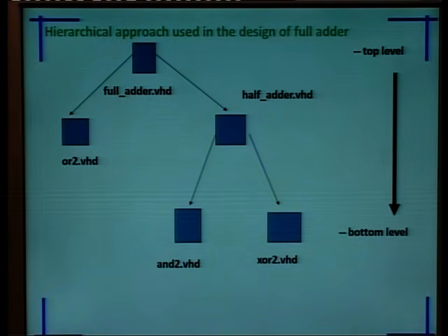In the bottom up approach, we have to start from the device, which may be NPN, MOSFET, PNP type, and from the device we go for the circuit design. From the circuit design we go for the gate level, and from gate level we go further for architecture and system level. That is the bottom up approach, but it is not followed in VHDL. For that we require a schematic type of editor like Tanner or Cadence or Synopsys type of tool.